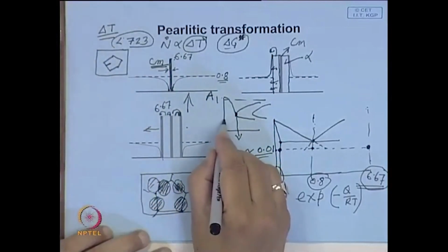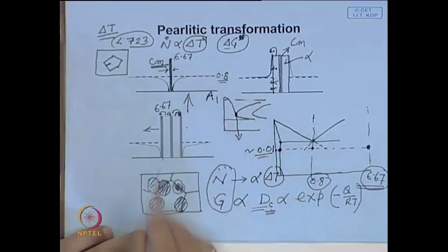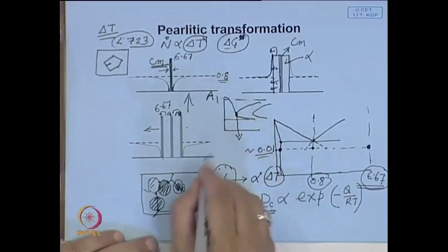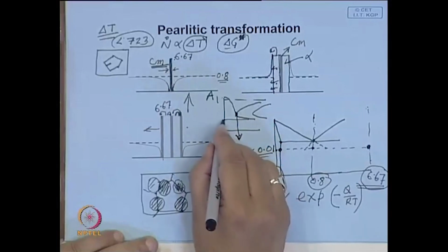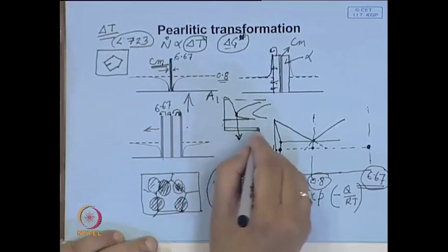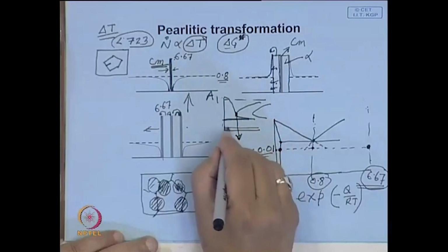austenite into pearlite through a diffusion controlled transformation. But if it exceeds that, martensite is something where we do not allow the diffusion to take place. So, that is why it is so fast, there is no C curve, you do not see anything, it is just parallel lines.